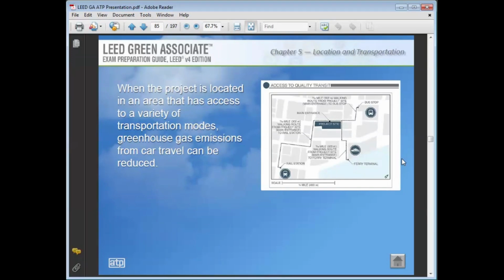Number one, that you have ample green spaces available with them. Number two, there should be some green patches, green areas where the infiltration of water into the ground can happen. And third, there could be a parking optimized space, or we may opt for having parking underneath the building, like parking in the basements. Since it will be built, obviously you will be excavating the site, and if you excavate the land or the site for like 5 feet or 10 feet, obviously if you can go a bit lower, you can have the foundations, the retaining walls, and a whole basement parking as well.